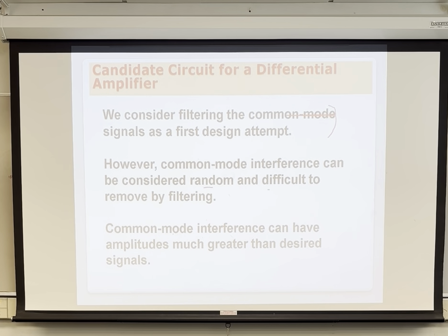Common mode interference can have amplitudes much greater than the desired signal. In the room we're in, what's a large common mode signal? Computer? Wi-Fi? The lights. There's 60 hertz common mode from the lights in here.